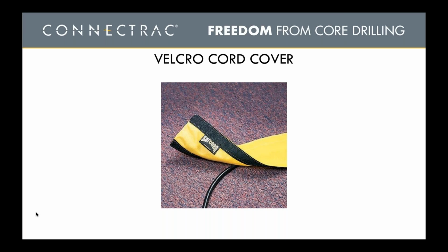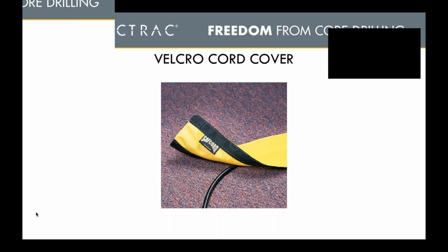In other words, according to one of the codes, and I won't quote these, if you want these numbers, I will certainly send them to you, an extension cord cannot be used as a substitute for fixed wiring. Another one of the codes in the NEC, the National Electric Code, the current code says this: every meeting room is required to have at least one wired, hardwired receptacle in the floor.